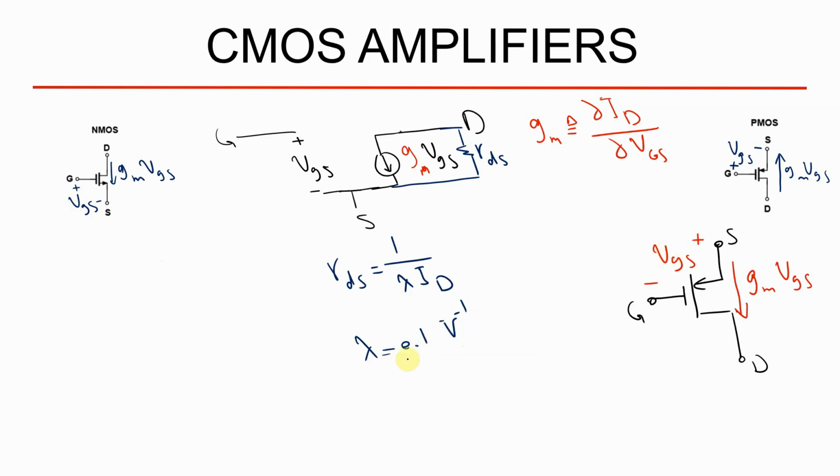Okay, this is just a simple example, and as you can see, by having the drain current of NMOS or PMOS transistors, you can get small signal parameters such as gm and R drain source for this small signal model. But VGS is varied and you have to use VGS to calculate the small signal parameters of amplifiers such as gain, input resistance or output resistance, something like this.